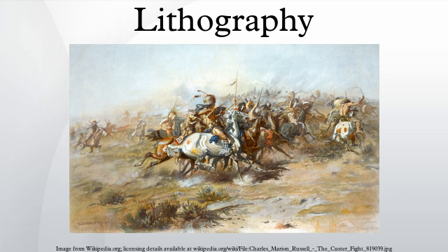Modern lithographic process. High-volume lithography is used presently to produce posters, maps, books, newspapers, and packaging, just about any smooth, mass-produced item with print and graphics on it. Most books, indeed all types of high-volume text, are now printed using offset lithography. For offset lithography, which depends on photographic processes, flexible aluminum, polyester, mylar or paper printing plates are used instead of stone tablets. Modern printing plates have a brushed or roughened texture and are covered with a photosensitive emulsion.